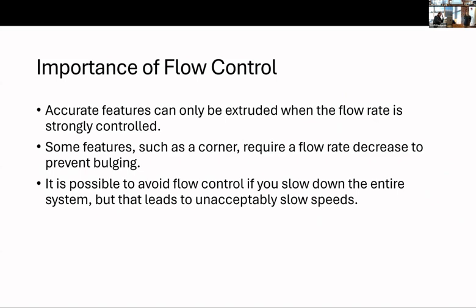So let's focus on flow control and why we care about it. Accurate features can only be extruded when flow rate is strongly controlled. And some features, such as a corner, for example, require a flow rate decrease to prevent bulging.